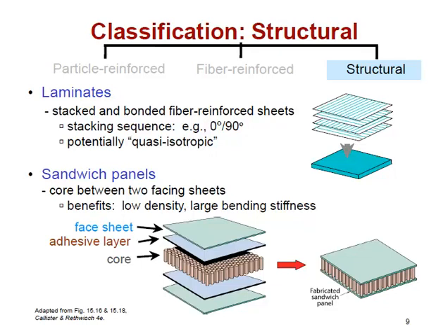The laminated, glued sandwich panel has mostly void space, and the components that it has within it are strong in two orthogonal directions. And it's very thin, so it can't really deflect much in shear between the two faces, and so that's really what gives its structural integrity. Again, possibly some of those subcomponents could themselves be composites with fibers, but the general advantage could be achieved even with monolithic materials.